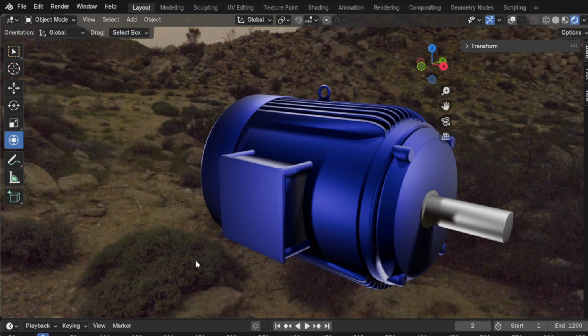So I had this compressor one time that was tripping the breaker, and I was kind of green, so I didn't do all of the rigorous practices you're supposed to do before you condemn one. I just yeeted a new compressor in there and found that the new one also tripped the breaker. Eventually I found that burnt connection, repaired it, and to my knowledge, that compressor is still running to this day. But that's a very expensive mistake, and it really hurts your reputation. So if I can help just one of you guys not make a mistake of that magnitude, that makes making this video worth it to me.